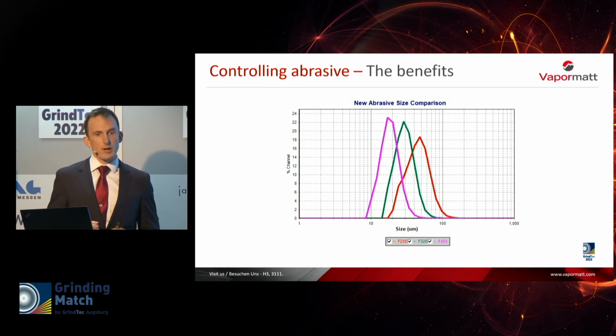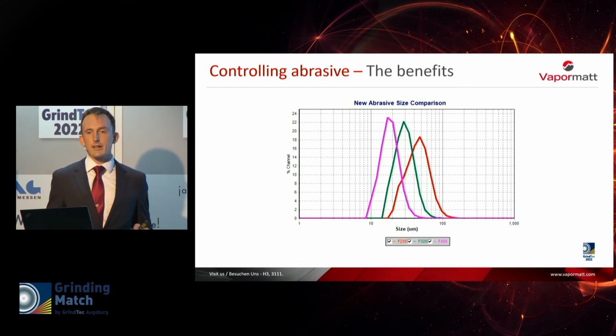However, once the fresh abrasive is in the machine, it begins to break down, and our bell curve and distribution becomes wider. The breakdown rate is somewhere between 100 and 500 grams per blast gun per hour. So there is a requirement to manage this and be able to remove the broken media as it is wearing down.